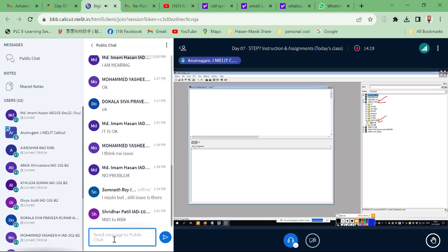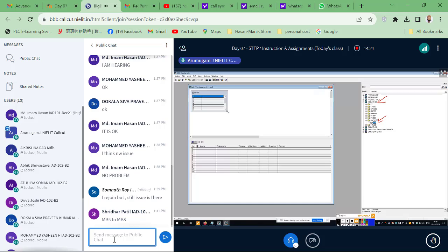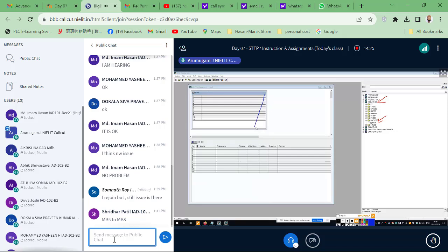Then double click. In the Siemens controllers, each rack, for the 300 and 400 series, has 11 slots. See, first slot to 11th slot. The first slot is always the power supply, or you can leave it empty, because empty means an external power supply is used. The second slot you always put for the CPU. That means it's counting from 0.